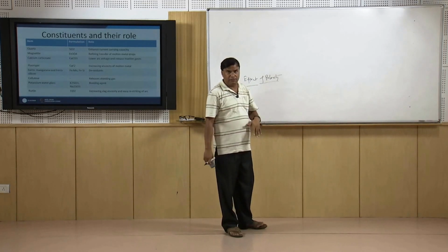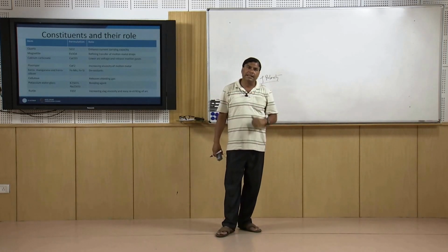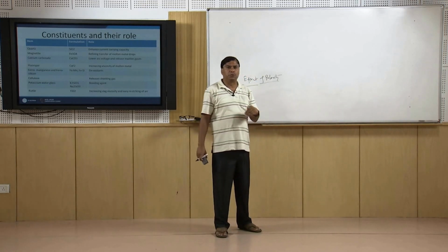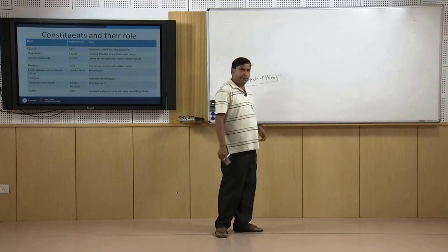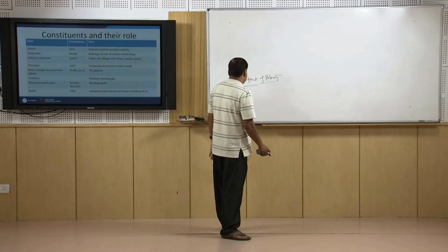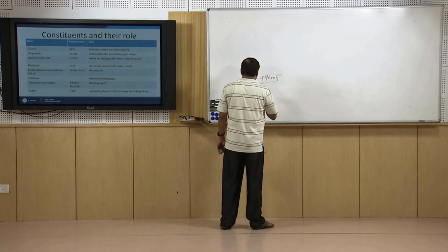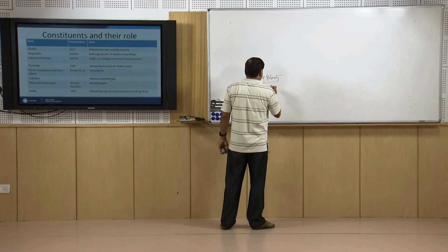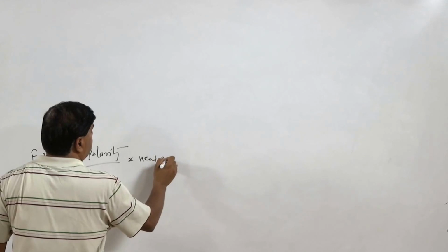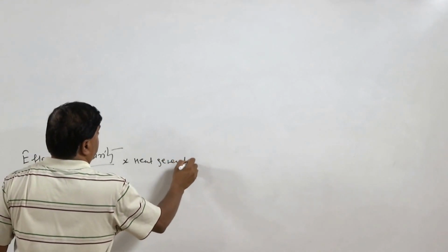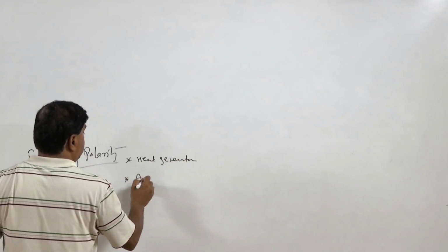If you want less heat in the workpiece side, like for the welding of thin sheets, in that case we will be choosing the reverse polarity, because in the case of reverse polarity, heat generation in the workpiece side is somewhat lesser. Now we will see another factor related to the effect of polarity apart from heat generation. Another important factor is the arc stability.